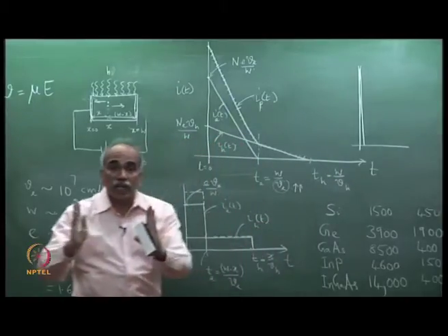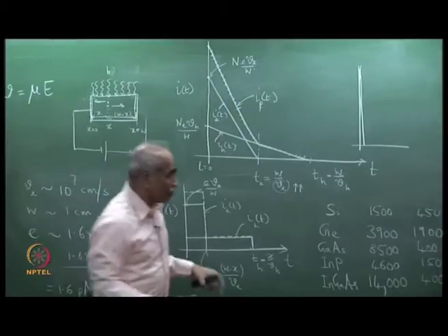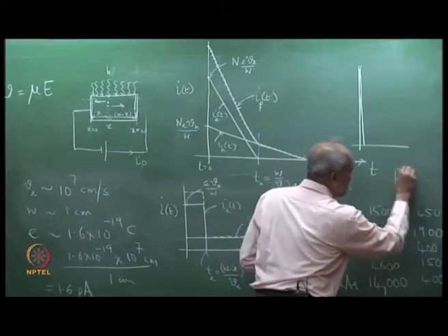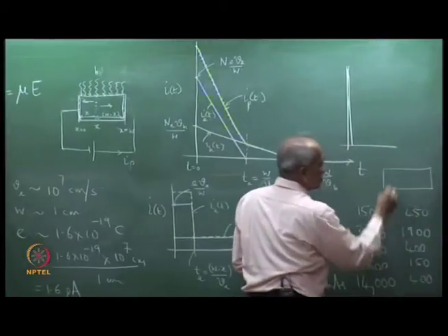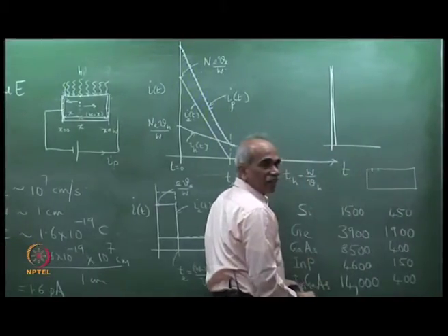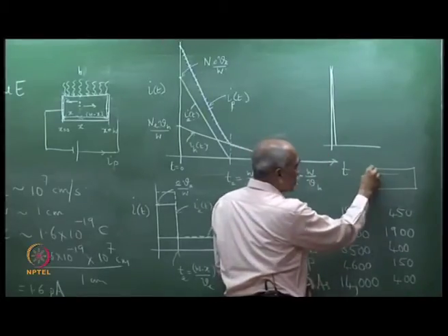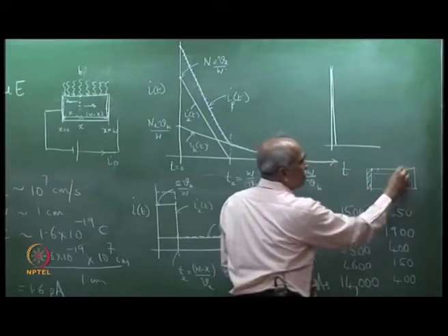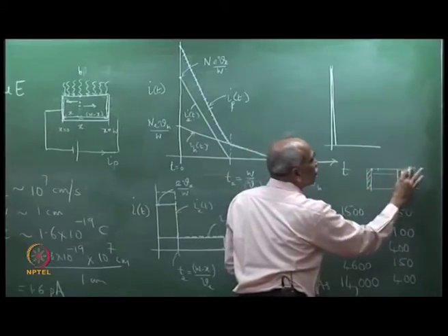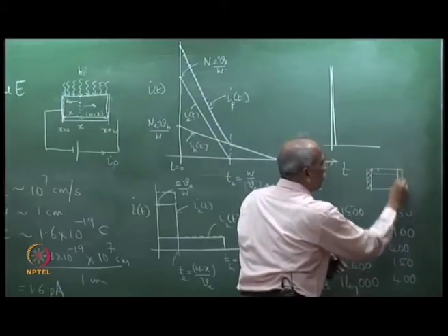So, if you can make T_E equal to T_H, how can we make that? It is possible that if this is the detector material, then you open a window somewhere here. Then you see the electron will take a slightly longer time, whereas holes are very close to the surface. Not that that is very good, but I want to avoid the pedestal.